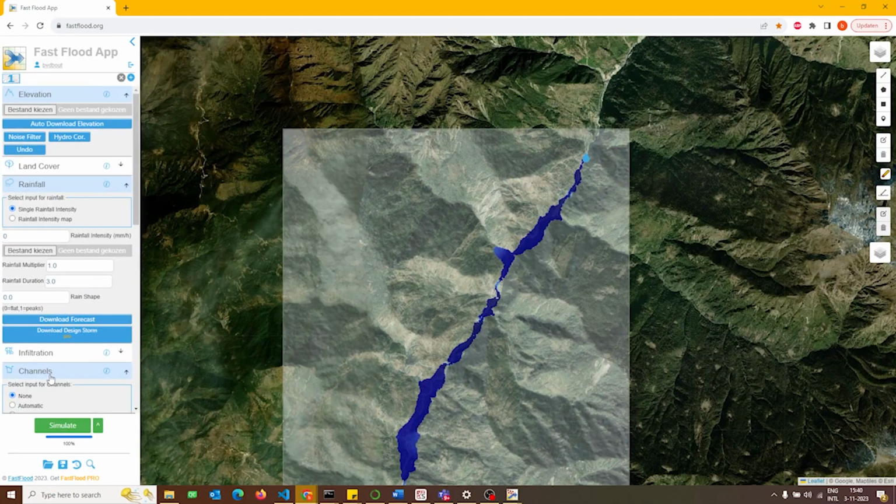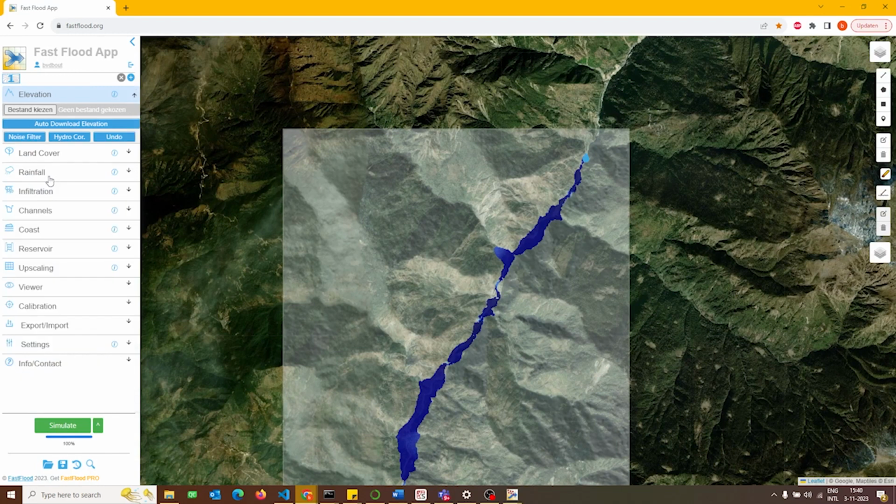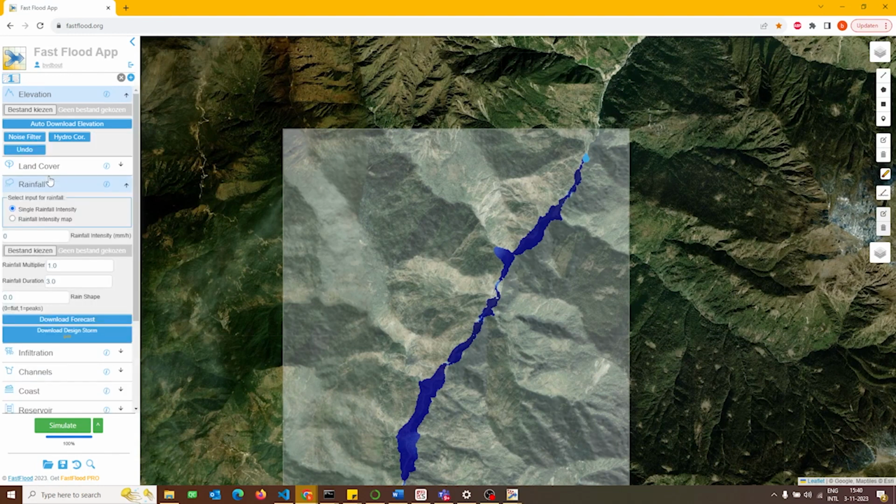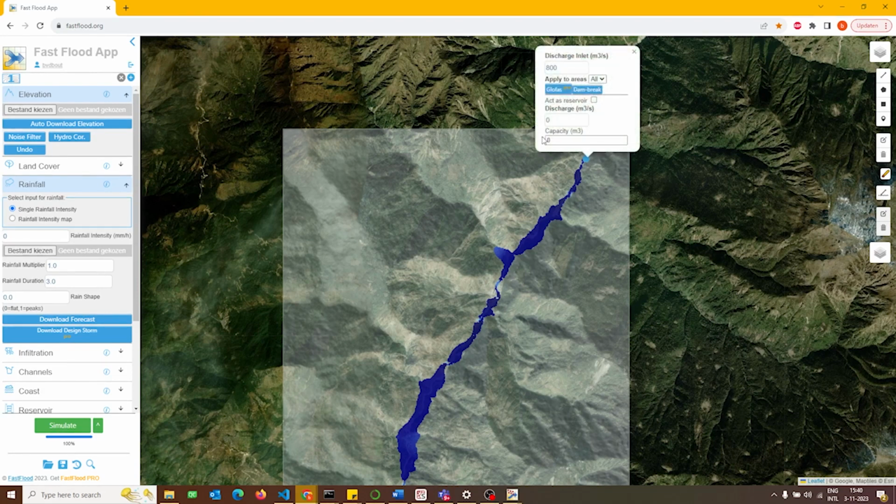Now, sometimes you don't have discharge data available. Maybe there's no station measuring discharge and global datasets don't have any data available. Now, there is a built-in option for you there. What we've done is we've taken the global flood forecasting model GloFAS and reanalysis data that was published as part of that, and we've done a return period analysis for that.